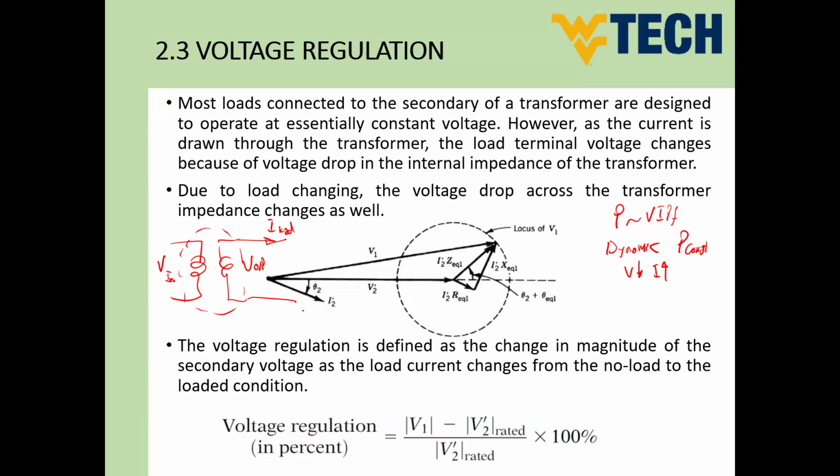How can we do that? There are a lot of techniques, like for instance, injecting some source of reactive power from the low voltage side at the load side in order to compensate the power factor and at the same time reduce the load current, and in this case the volt would be better, or the volt drop across the transformer would be less because we reduce the inductor current.